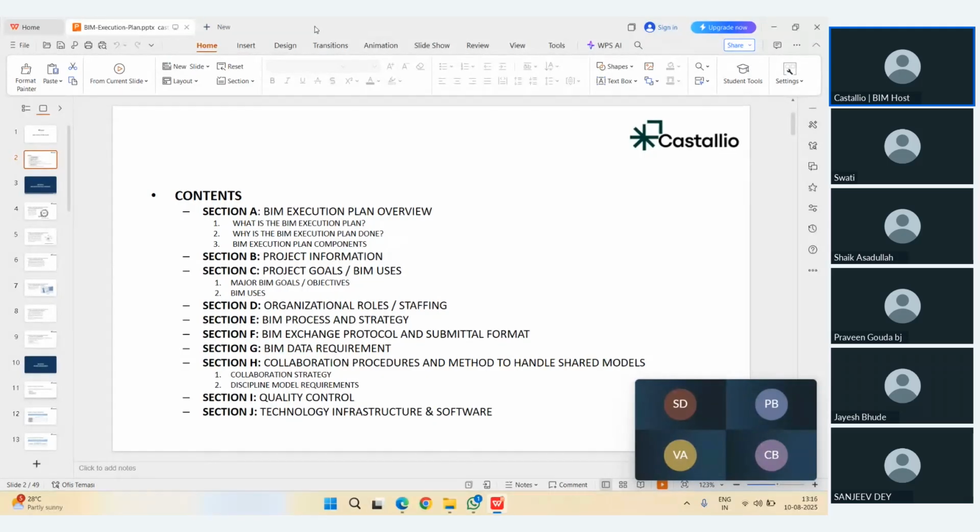So basically, there are some standard protocols that have to be given to each and every contractor or consultant to submit their data. If it is a sheet, they will submit all the sheets in DWG file format. If it is a model, then of course they need to submit the original or native model in .rvt file format. Or if you are conducting coordination meetings, they have to submit either an .ifc model or an .nwd model. This particular extension, what I'm telling you, is the standardized process we are following under the exchange data format, which we will discuss again in detail.